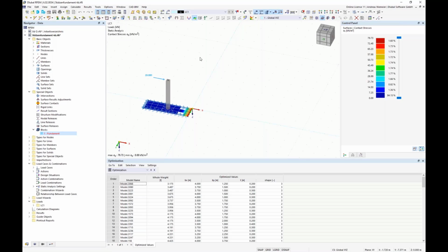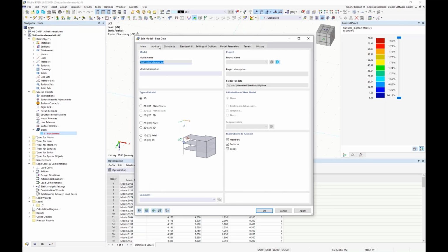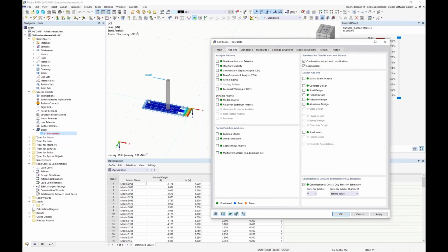Further, you can use this not only for load cases but also for all activated designs. So if you say I have to do concrete design for this structure with reinforcement, then the program shows you only possible solutions if the design add-on gives green light, which means a utilization smaller or equal to one.